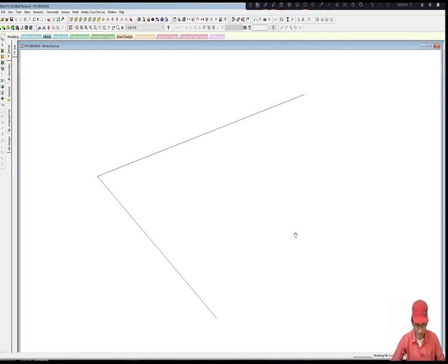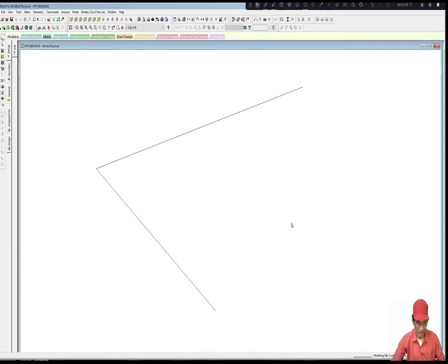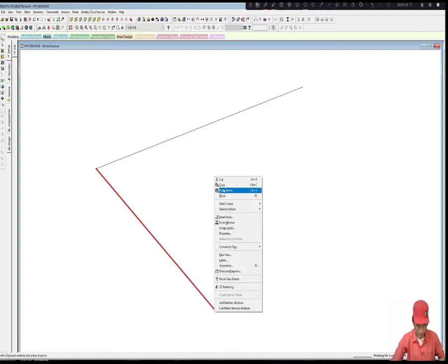I am not using this grid line to create my buildings. I have taken help only to create my first 2 lines. This is because we might not be able to create unequal grids in STAAD Pro. So now to create my building, I copy this line and go to paste beam.